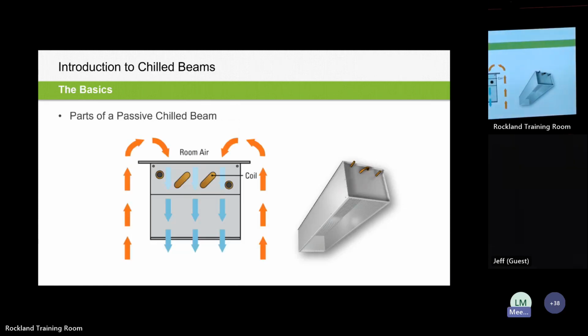And then again, the passive beam. So this usually needs some amount of free area on either side of the passive beam footprint to allow for that warm air to get up into the ceiling void, or if it's exposed, just up around that passive beam to cool off. So you might put these above high heat equipment, or in walkways or near the perimeter where you need additional boost of cooling. And we've seen these implemented with all air mixing systems or underfloor displacement style air distribution systems, so they can be mixed and matched as well.